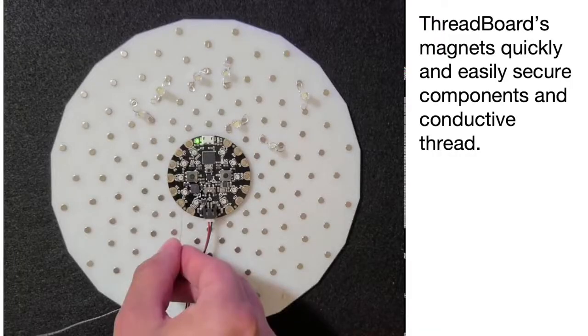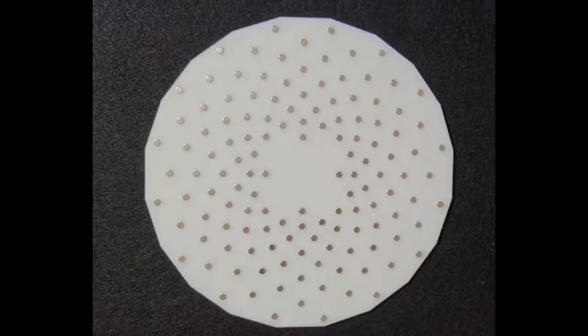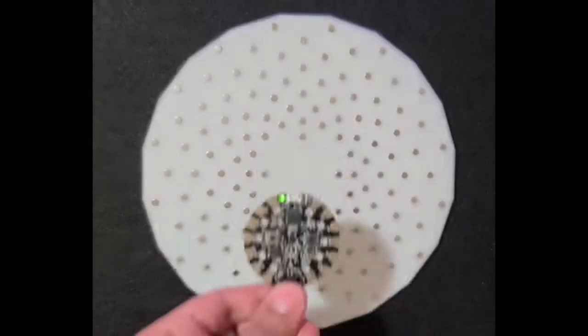In this video, we can see an example project called the Big Dipper, where several LEDs and stainless steel thread attach to the microcontroller to make the circuitry. In the video, you can see me populate the board with 7 LEDs and then lay the ground bus on the outer layer of the magnets, and on the inner circle of magnets I lay down the power bus. Then I connect the LEDs to the buses to power them on.